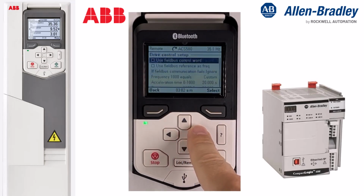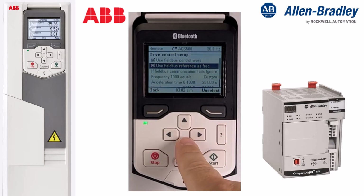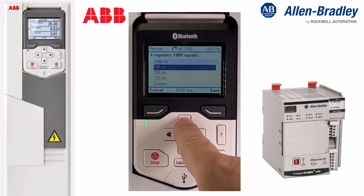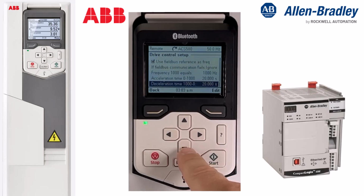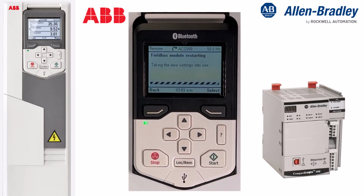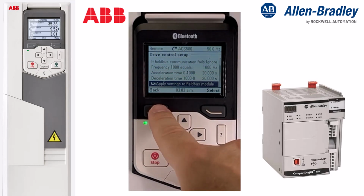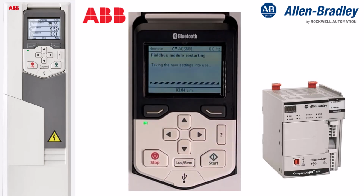We'll first choose Field Bus Control Word and then Field Bus Reference, and then scroll down to Frequency 1000. We'll choose 1000 here to make a 1-for-1 scaling, and then come down to the bottom and apply settings to Field Bus Module again. Then we'll go back, come down to the very bottom and apply settings one more time. Click back.